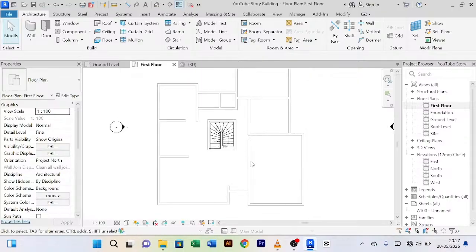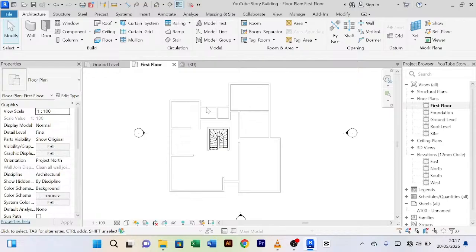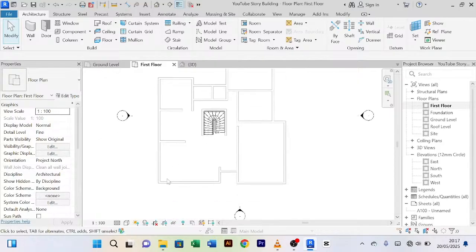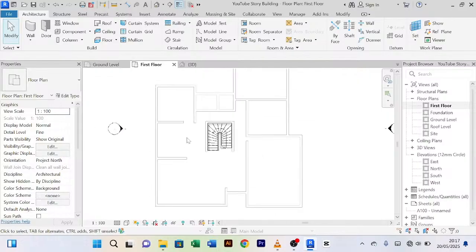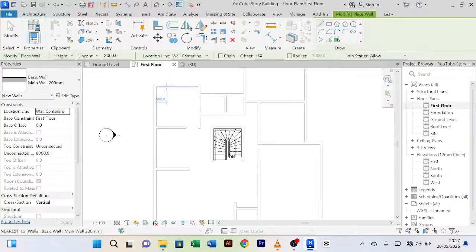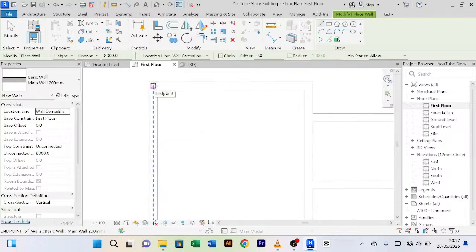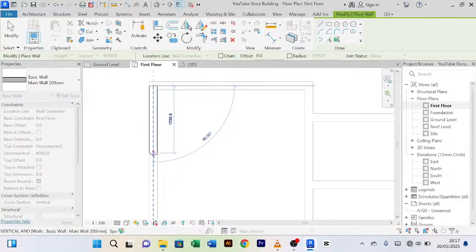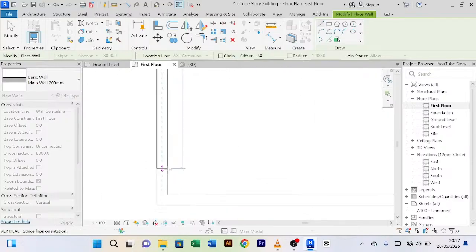So now we're going to create our walls here. I'll just create something simple following these walls. I will not do a lot of measurements here. So we come to our wall, we select wall architecture, and it has selected the wall we created for the ground floor. We could even just sketch by picking lines, but I want to draw. I make sure these dotted lines are in the middle of this wall so that the wall we're drawing doesn't go offline.